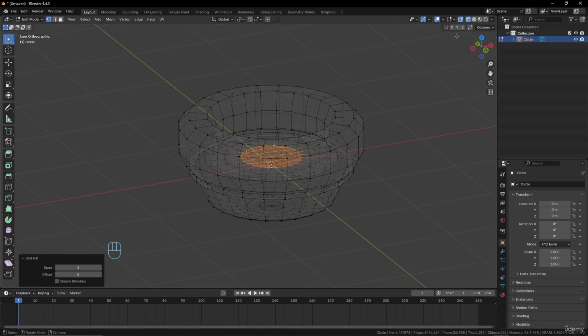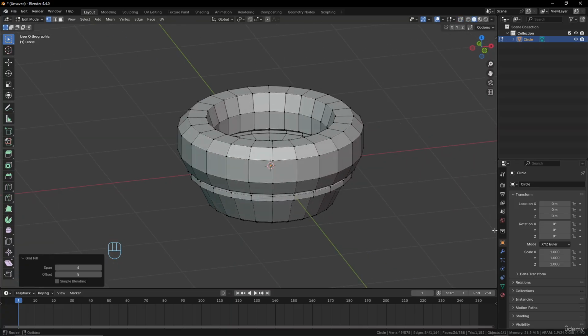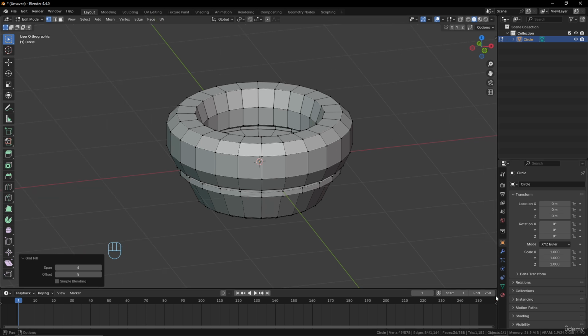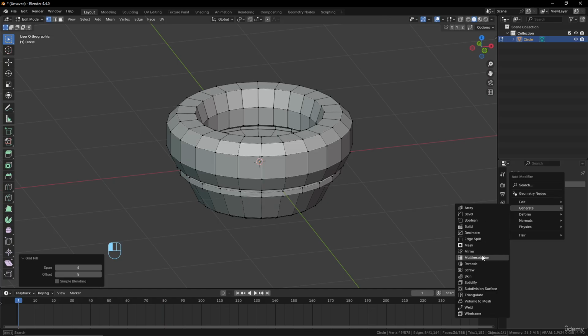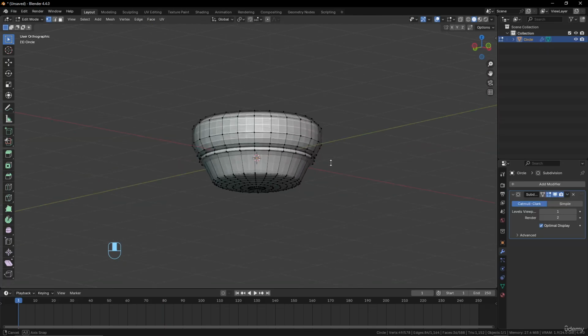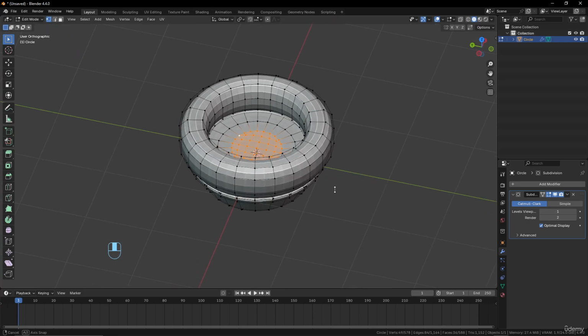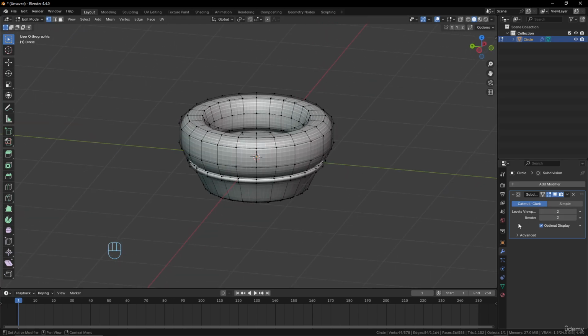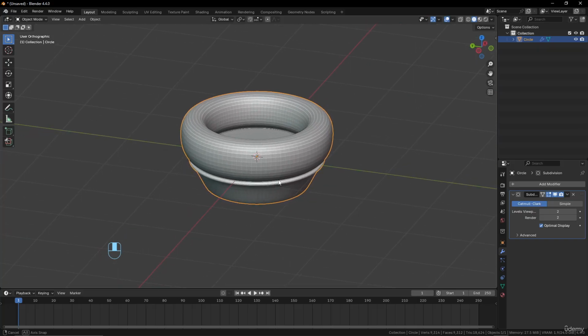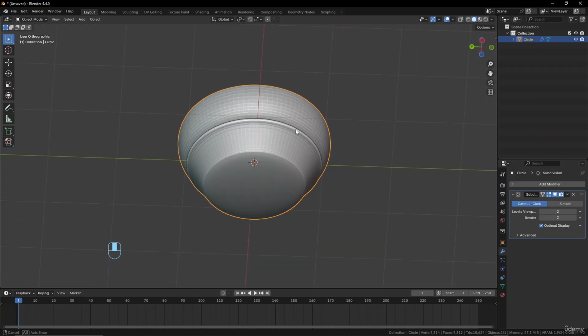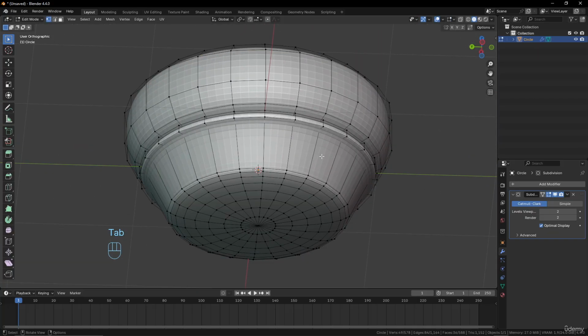Good. So what we can do is watching that here in the viewport shading solid view, and now we will add a modifier, and this modifier will be a subdivision surface. So now we will have this kind of shape, okay? We could even increase and watch here how it looks already. So, okay, it looks nice. We have already a nice shape.